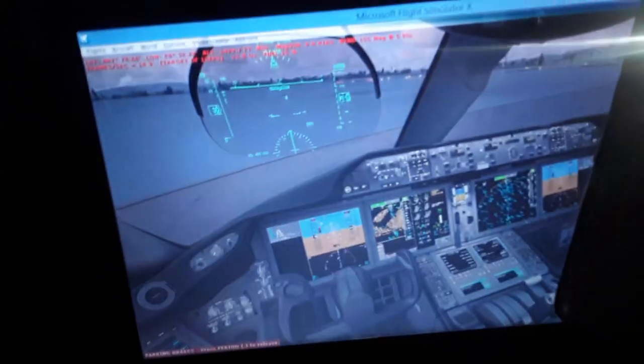We're gonna have a pitch attitude of 9 degrees for takeoff with 50 degrees of flaps and 4.25 degrees of horizontal trim stabilizer. We're gonna have also the SIDs, the standard instrument departure waypoints and fixes that include horizontal and vertical navigation fixes and altitude and speed constraints for the initial climb of the aircraft after departure.